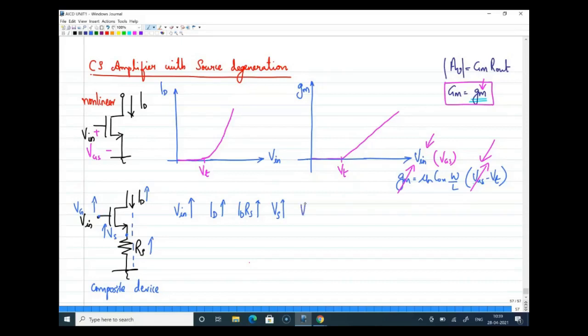What is the meaning of that? The Vgs term will be almost remaining constant. Will you agree with me? As Vg increases in a circuit, when you place this in a circuit, finally Vs is also increasing. As a result, Vgs will tend to remain constant, right? If that is the case, if I consider a loop here, how will I write it?